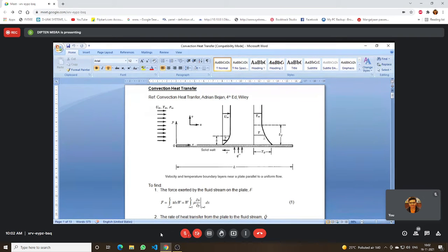Even though temperature is varying, the density does not change much within the range of temperature that we deal with in convective heat transfer. For most cases of heat transfer, we take a very limited range of temperature within which most of the physical phenomena happen. Suppose it is a hot billet being immersed in a cold fluid, whatever the case, whenever there is heat transfer, most of the cases we deal with involve a temperature varying within a limited range.